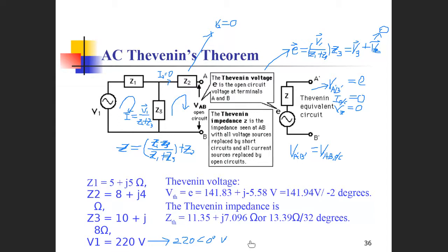Please test yourselves by doing these examples. You simply bring in the impedance values Z1, Z2, Z3, and V1, so you can find the equivalent impedance Z and the equivalent internal electromotive force E. As practice, check your understanding of complex number calculations. Once again, for summations or subtractions, you can use complex number forms. When doing multiplications and divisions, I suggest using polar forms. Therefore, for each impedance and each voltage, you can write them in both polar form and complex number form.